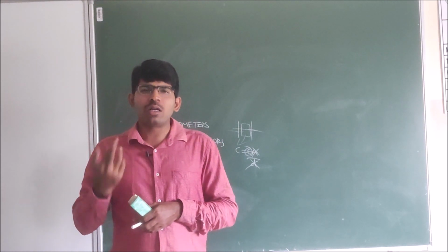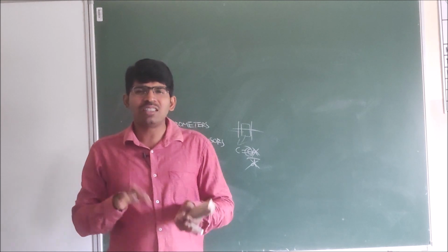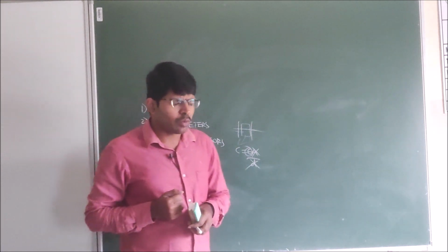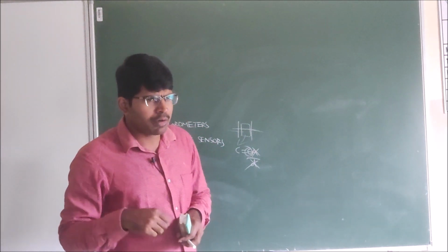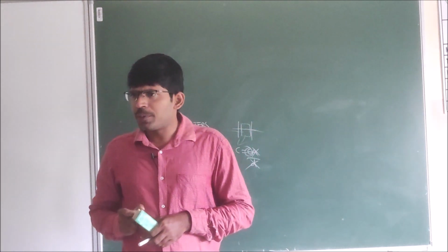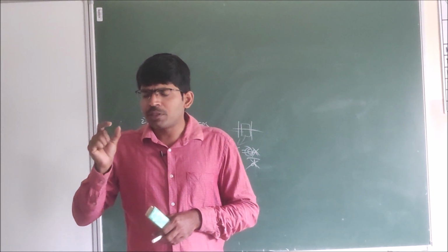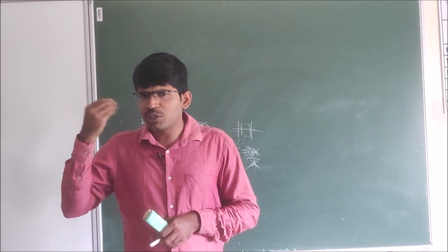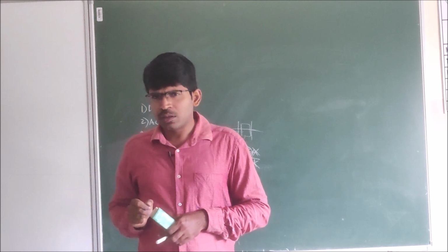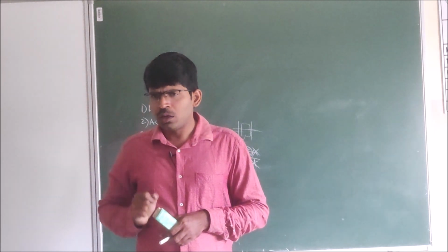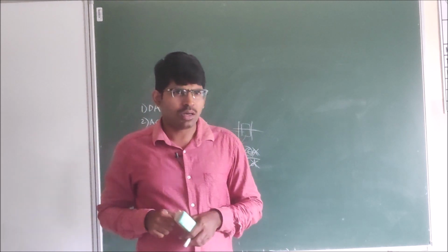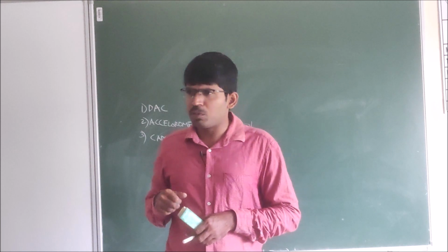So we have to convert this. Converting does not mean we are changing this current to voltage; that you have to remember. We already discussed this in the voltage to current converter also. Whenever we mention a converter, we always mean that we are representing the equivalent voltage which is measurable by us. So when the current is changing, which is very small, the voltage change we observe can be measured, but the current change cannot be measured by us.